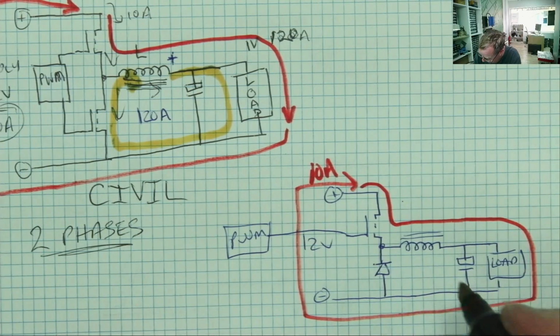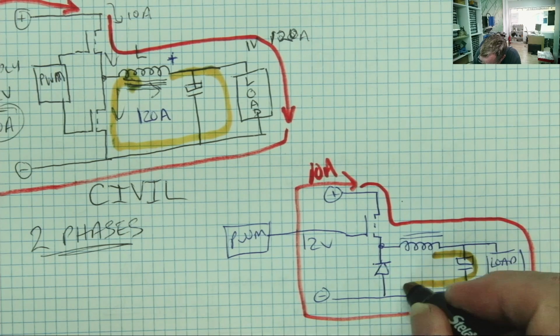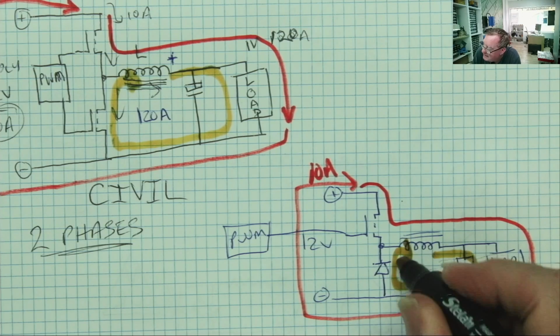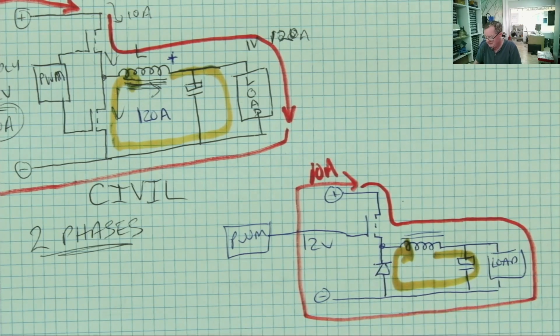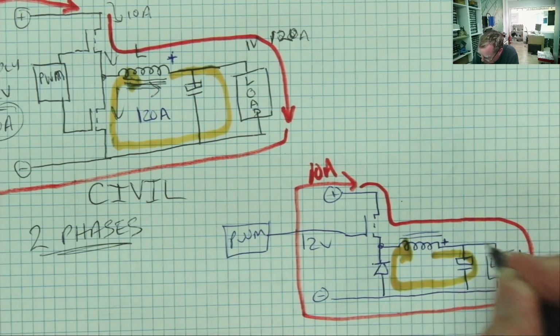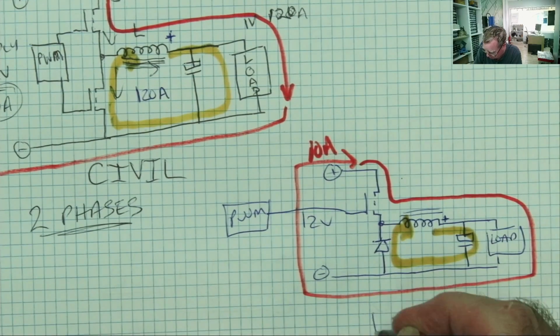And we still have, from the coil back through this diode, notice in this direction this is forward biased, okay? This end is more positive than this end because this is now the positive supply, the coil, and we have that circuit. That's a buck converter.